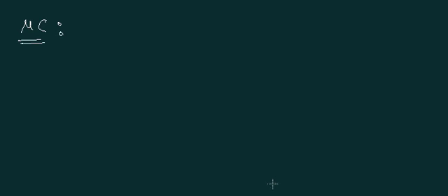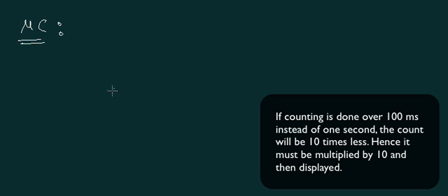We look at the microcontroller, how the microcontroller is going to handle the square wave that is given to it, and then produce the output display of some number with some units and so on. Now, the fundamental idea is to measure the frequency. So, we have to do counting over 1 second typically, or 100 milliseconds.